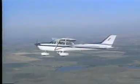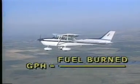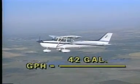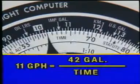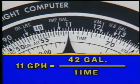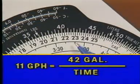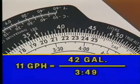Another type of fuel problem is to determine your endurance, or how much time you can stay aloft. Assume your airplane has 42 gallons of fuel on board, and it uses 11 gallons of fuel per hour. This time, set the index under 11, which is the rate per hour. Under the 42, read 229 minutes, or 3 hours 49 minutes on the inner scale.